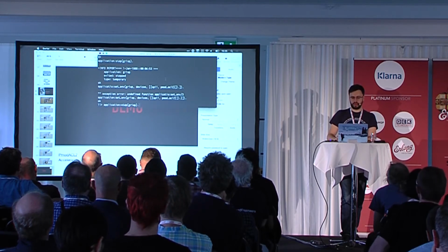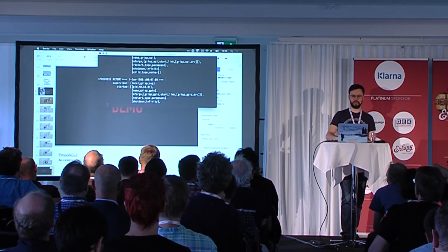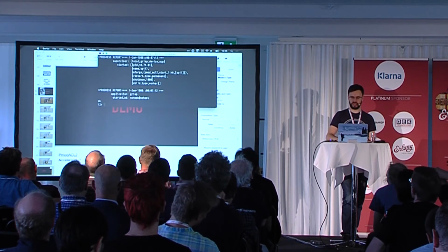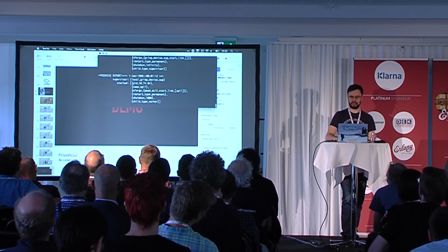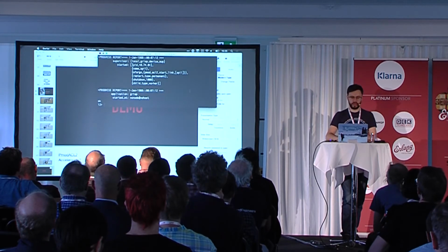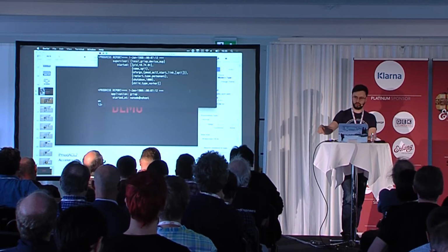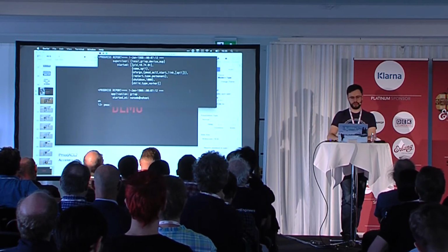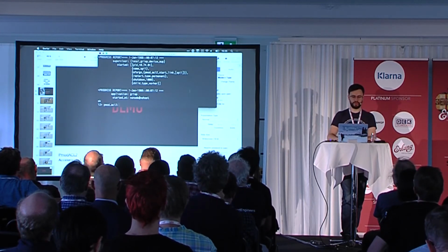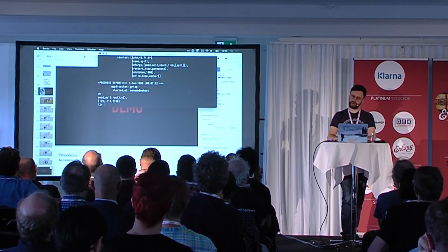So we told GRiSP about this, and we're now going to start the GRiSP runtime again. And what we can see here, after a while when all the basic stuff has started, is that this PMOD ACL2 driver has also started. Because this one has started and it knows which port, I told it which port this PMOD sits on, you can now use this module, and let's call this function first. Oh, there's some values there.